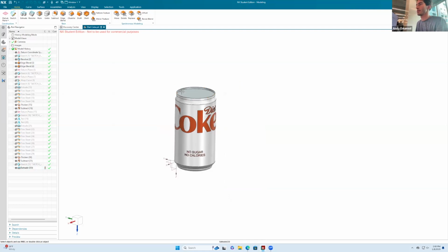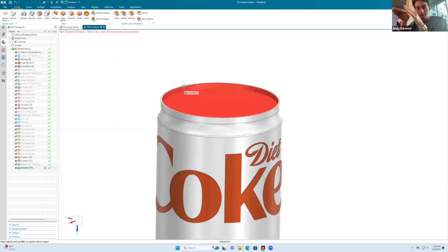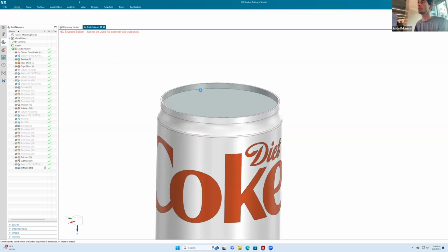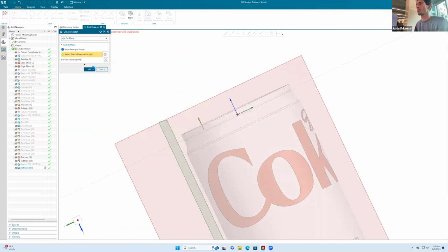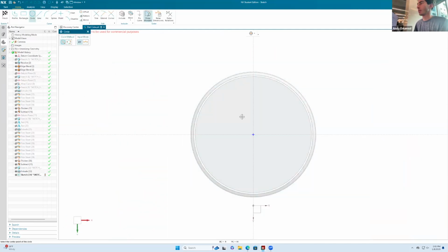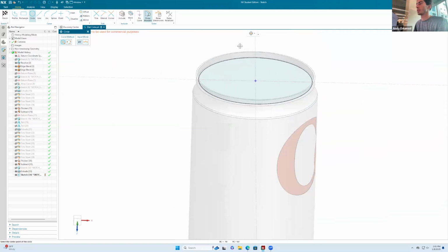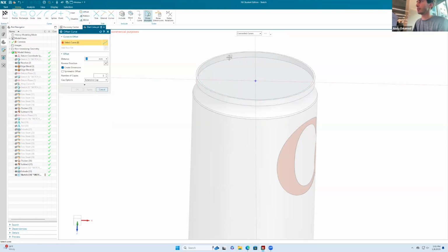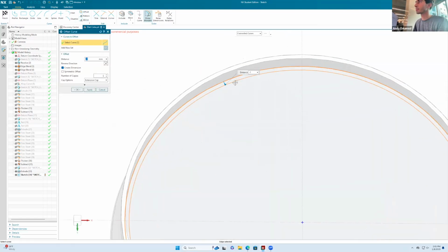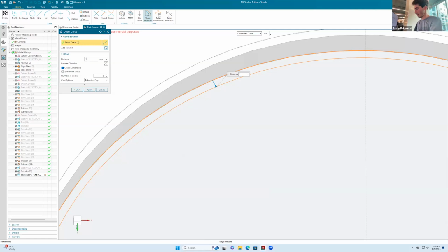I'll hide. But now there's that little chamfer area. We're gonna go here to sketch, over here to circle. Actually, we could have just offsetted that circle, by negative, this is -1, as we originally had it.